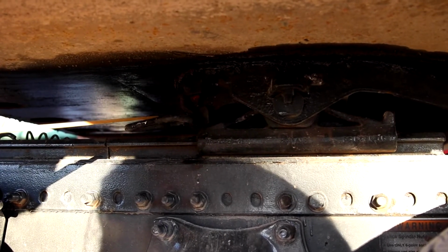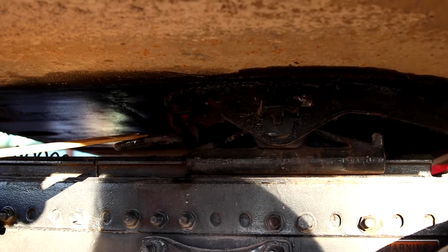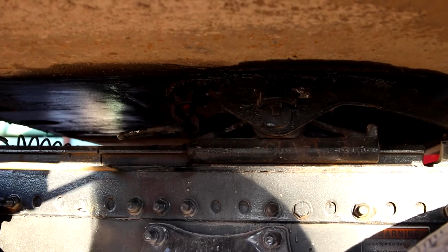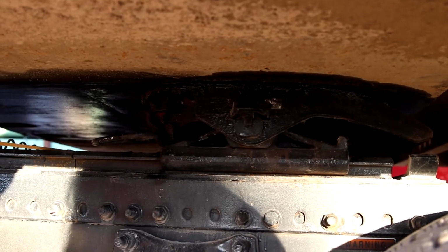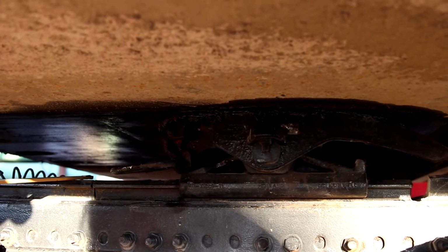The fifth wheel is in the locked and travel position. It's mounted securely to the vehicle. It's not damaged or broken. This particular truck has a sliding fifth wheel, so check and make sure that the locking pins are locked, or the fifth wheel will move either forward or backwards on you.